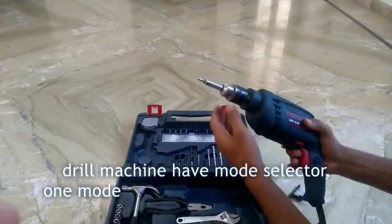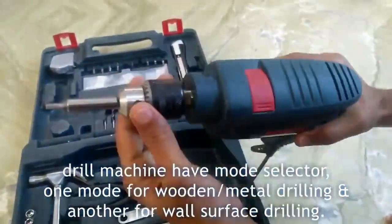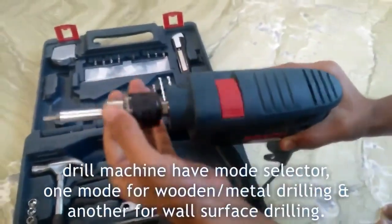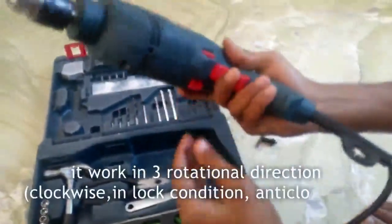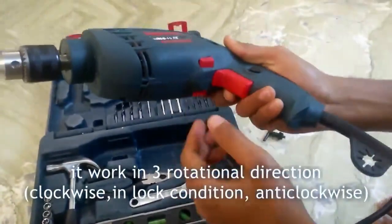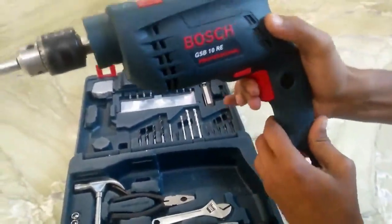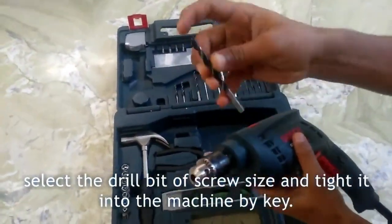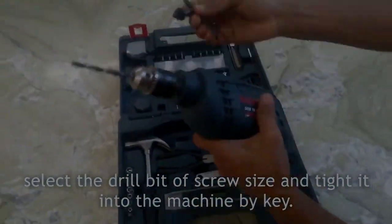Now let's see how to use the drill machine. It has two modes, wooden at this end and wall at the other end. So it works in three directions: clockwise, that is forward, the lock condition, and anti-clockwise for the reverse direction of the drill machine. Now let's see how to tighten the drill bit. Select the desired drill bit size, tighten it by hand initially, and then using this key, tighten the drill bit.